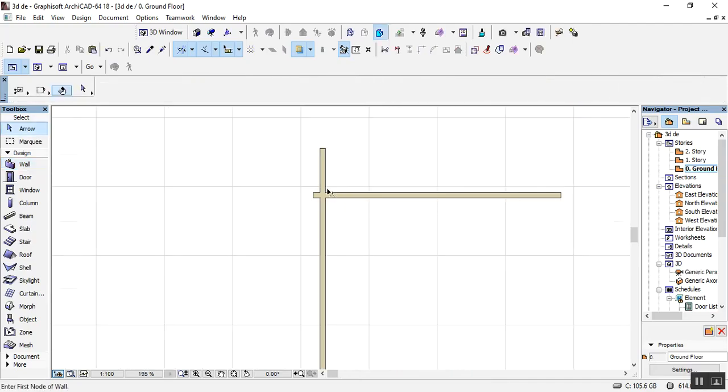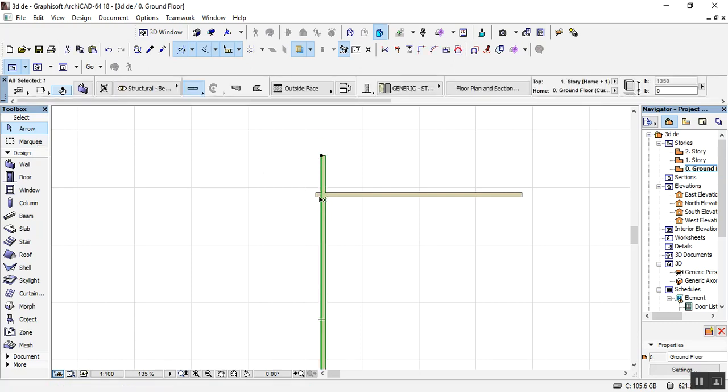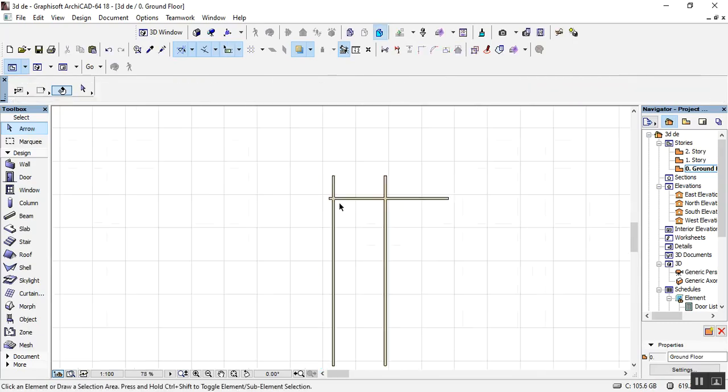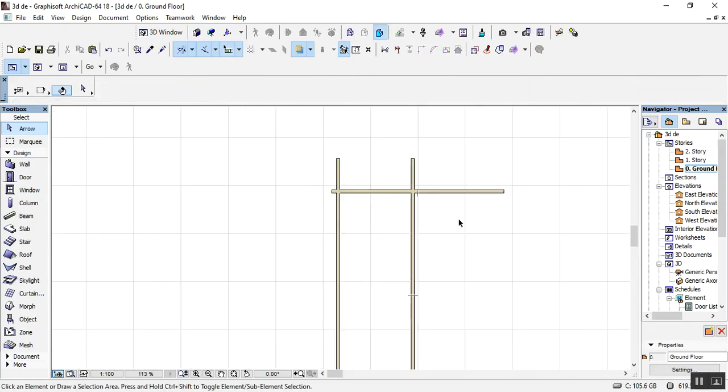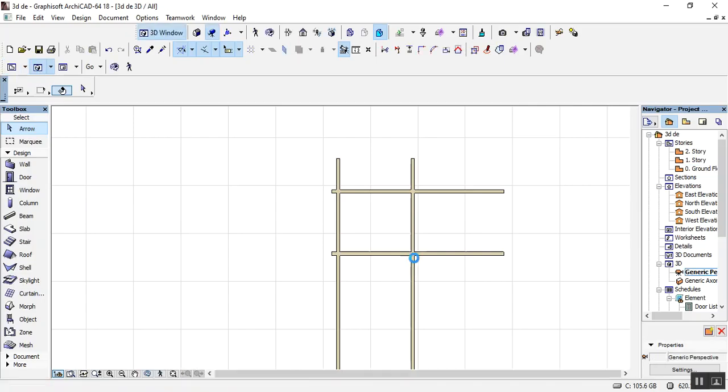So whatever you want to do a design, you don't need to go back to this wall to change settings and start measuring. You could just copy this wall like Control D, Control plus, you move your wall to the desired places you want it. And you can create multiple walls with these. You can create from this way, and you can also create from this way, same multiple walls, the ones you want. So let's see that on our 3D view.